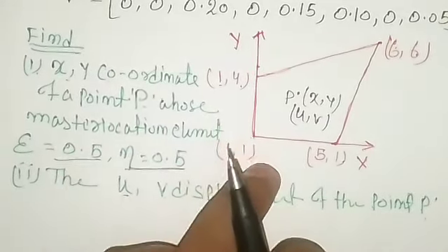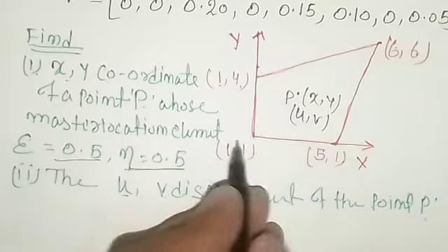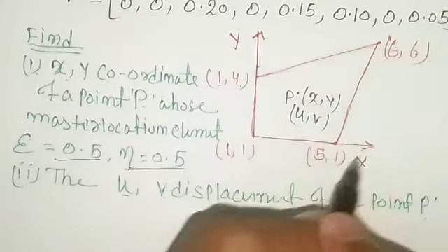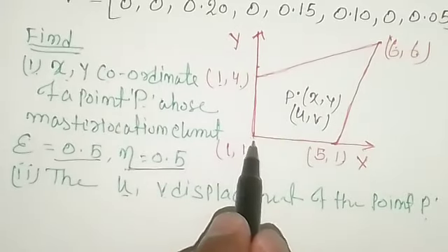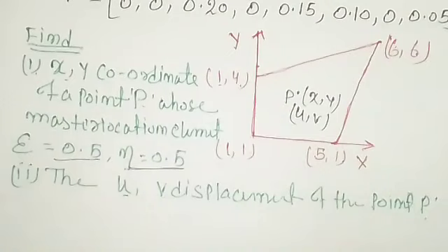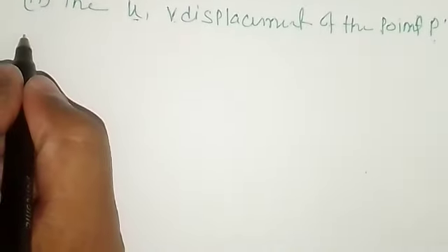First of all, we will find the shape function at each node, that is N1, N2, N3 and N4. So this is the quadrilateral shape. For that we have to use 1 by 4, 1 minus psi, 1 minus neta, as you know. So here we have a solution.